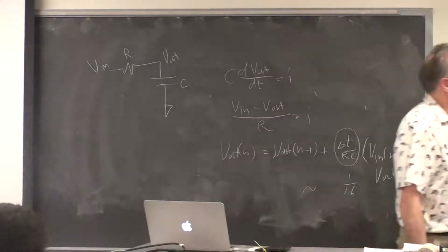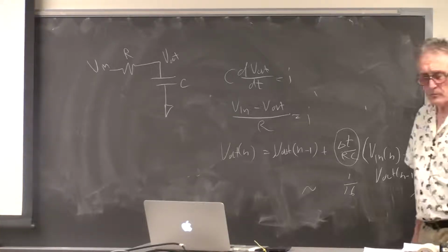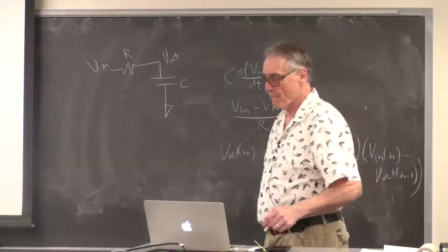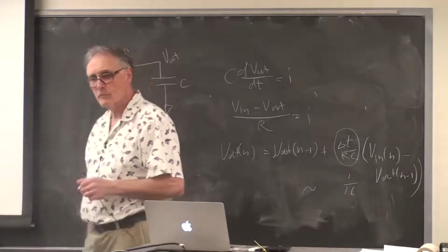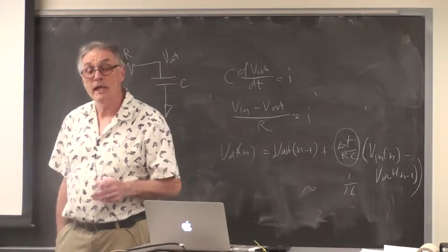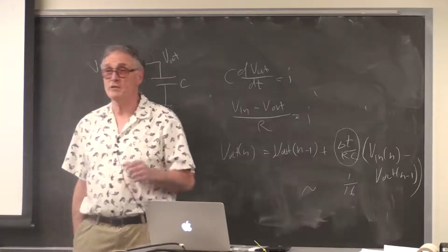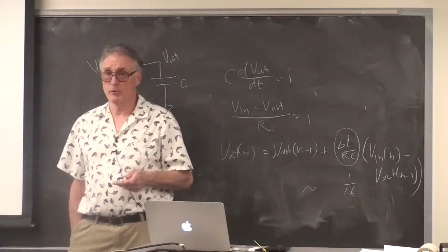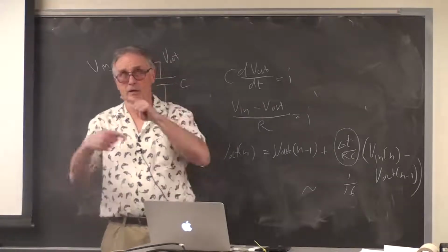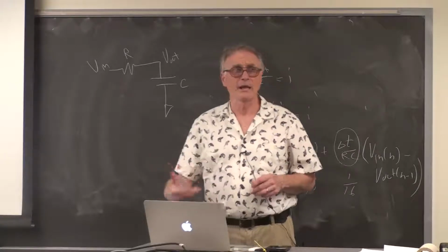Because a shift by any number of bits in this architecture is one machine cycle. What is the difference between multiplication time and addition time? Addition time is one cycle. Multiplication time is 2 cycles for a 16 by 16 multiply. A 32 by 32 multiply requires 4 of those, so it's 8 cycles, and a couple of adds, 3 adds.